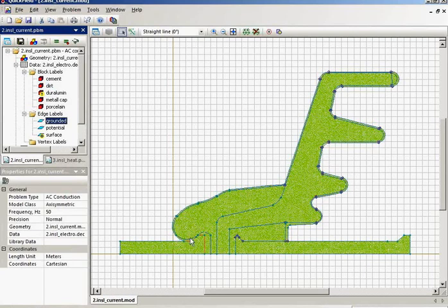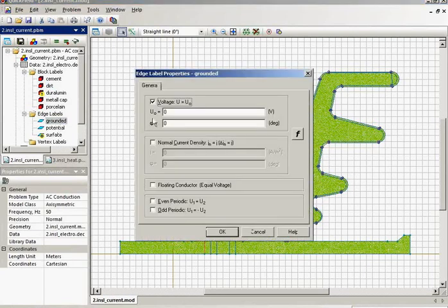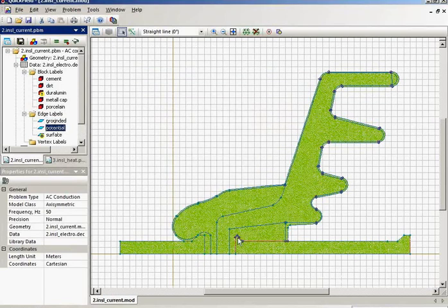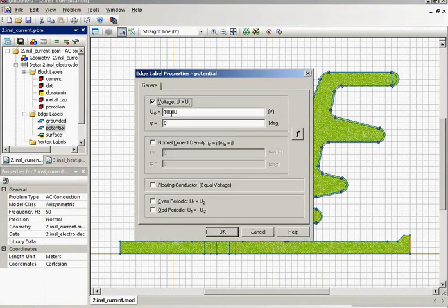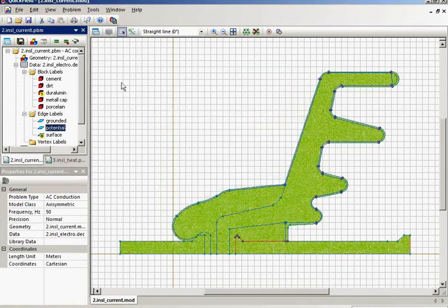This is the grounded part with zero voltage, and this is the high voltage part, 10 kilovolts voltage. You know, it is required about 10 insulators for a transmission line of 110 kilovolts, so it's about 10 kilovolts per one insulator.